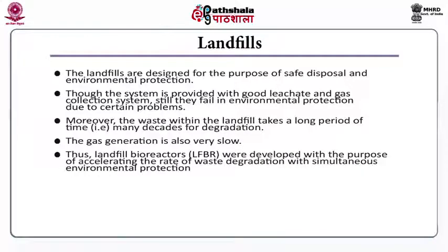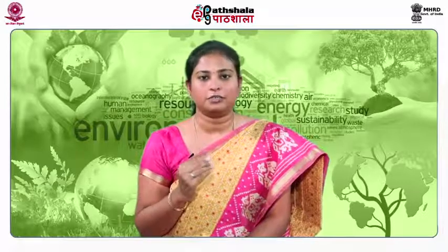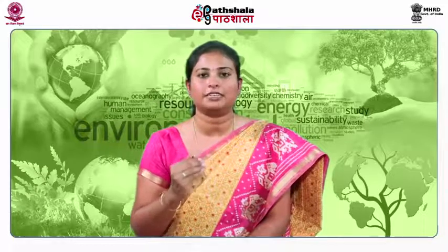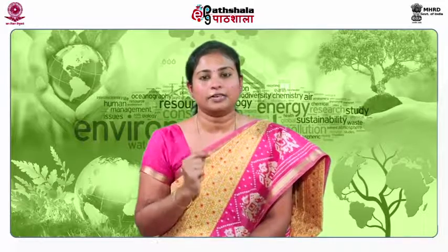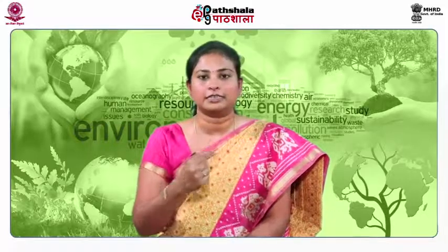Thus, the concept of landfill bioreactors was developed with the purpose of accelerating the rate of waste degradation with simultaneous environmental protection. So, a landfill bioreactor is an engineered landfill developed to speed up the process of waste degradation and promote environmental protection through a proper gas and leachate management system. Waste stabilization occurs within 5 to 10 years of implementation, but it requires a minimum of 35 to 40% moisture to increase the rate of waste degradation.